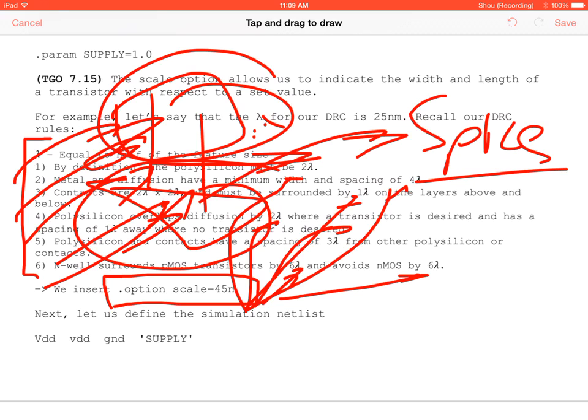And you're going to do this in these labs that are coming up. You're actually going to do a layout. It'll generate the SPICE for you. Then you're going to simulate the waveform. And based on the simulated waveform, you're going to see how your circuit actually works.